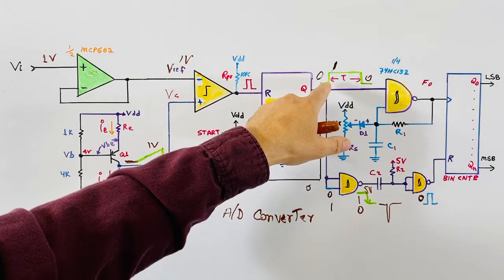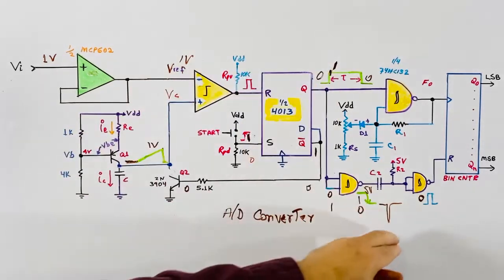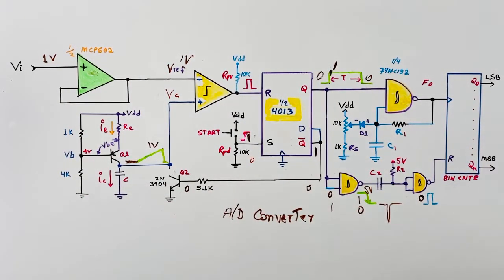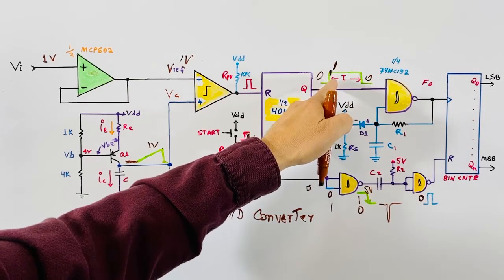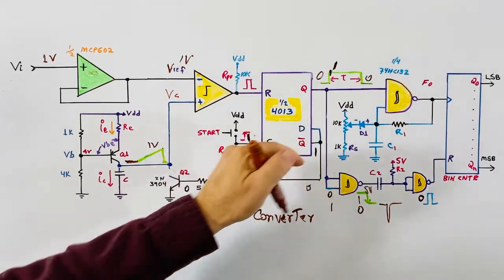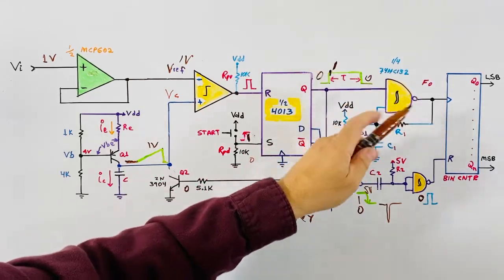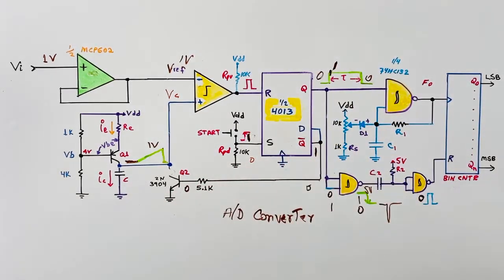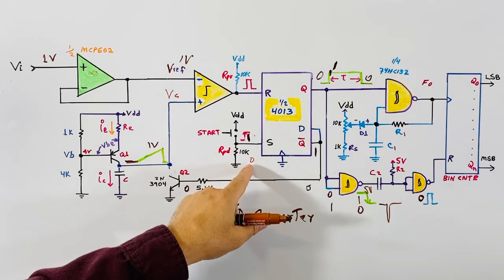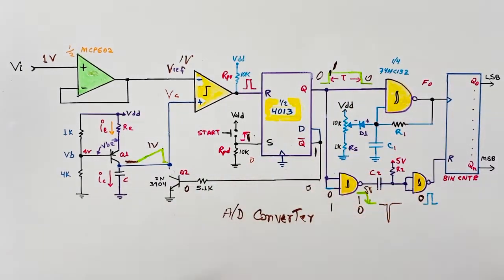That means that during the time t, in the first fraction of time right here, a reset pulse was applied. That way the counter started with zeros. When the T pulse ends, which is proportional to this time, the gate goes to zero, so the oscillator stops sending frequency, and the count will stay there. And the circuit is waiting for a new pulse to arrive to start a new conversion. So when this one ends, the conversion is ready and the number will be there.